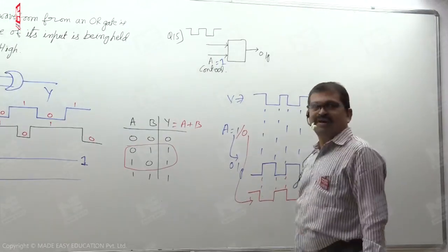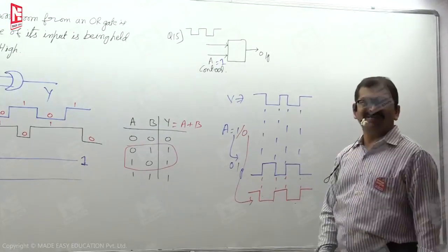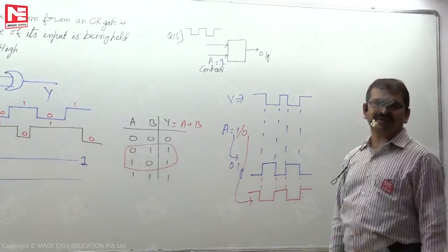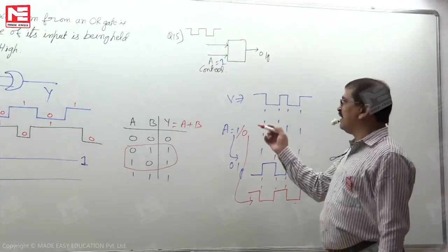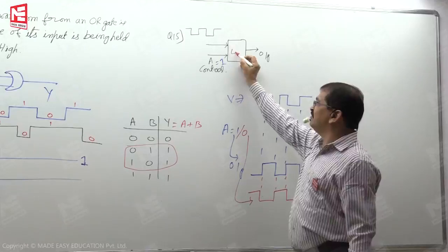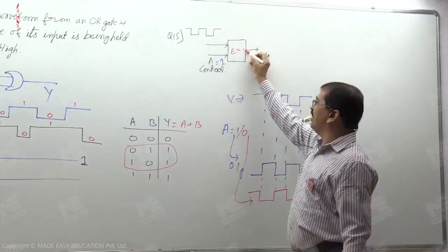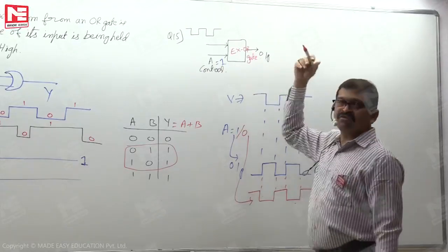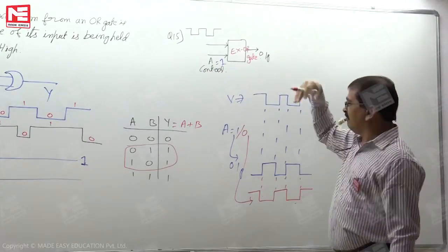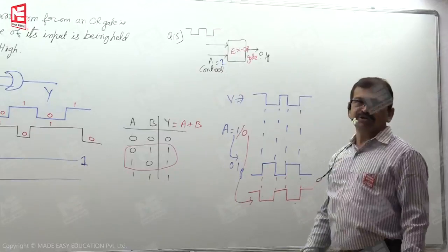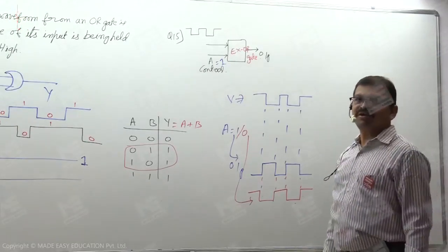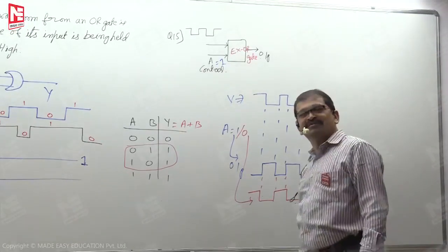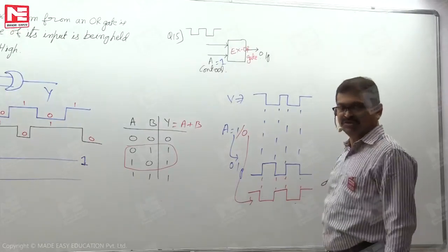If you remember the exclusive OR truth table well, the results we mentioned with it are possible if and only if the black box has an exclusive OR gate. The exclusive OR gate gives the inversion operation whenever one of the inputs is 1, and gives the buffer operation whenever one of its inputs is 0.